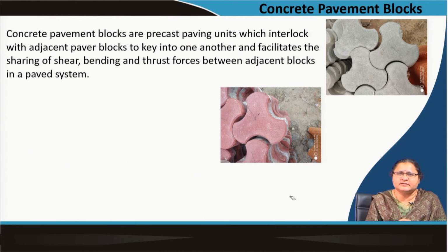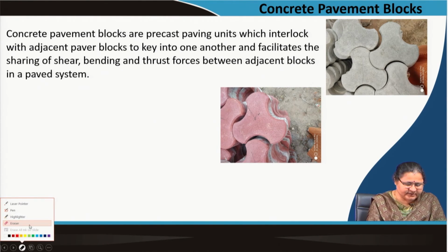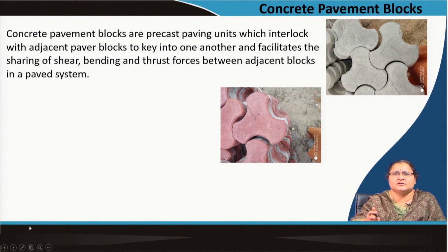Many lines pass underground, mostly following roads, and whenever you need to, you can access the ground beneath without breaking anything. So, these are recommended, and this interlocking helps in sharing the shear, bending and thrust force between adjacent blocks, and finally the load is shared to the ground.